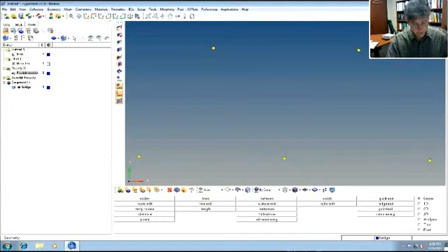You can actually use control and the left mouse. Oops. Let's do it again. I do it so subconsciously. If you hit down control and move the left mouse button, it lets you rotate. If you hit control and then the middle mouse button, you can zoom in on things by doing that. You can actually sketch the zoom window. And if you do the right mouse button and control, it lets you pan. All right? So you can do that dynamic stuff, which is kind of nice.